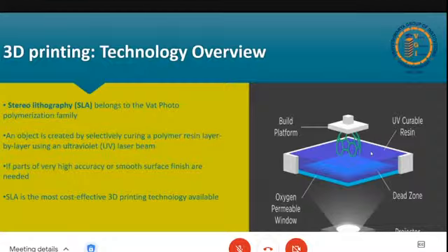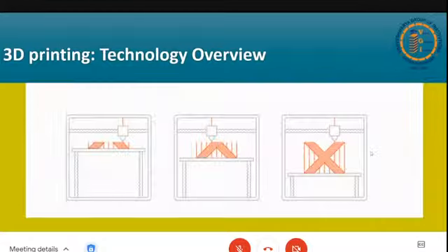In FDM, even if you use a very fine nozzle to print, you can switch nozzles. If you're printing with a 1 mm nozzle, it's just like printing with a permanent marker, which has a very broad tip. If you are writing with that, you will not get very good detail. With a fine nozzle you can make very small features and small holes, but it will take a lot of time to fill the same area that you have filled with the marker.